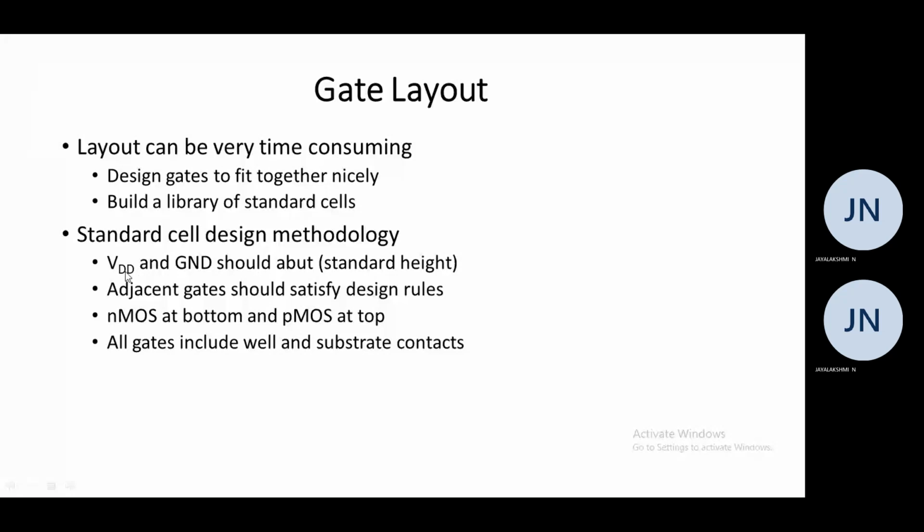Usually, the VDD and the ground should be in standard height. Adjacent gates should satisfy design rules. The NMOS should always be at bottom and PMOS should always be at top. All gates include well and substrate contacts.